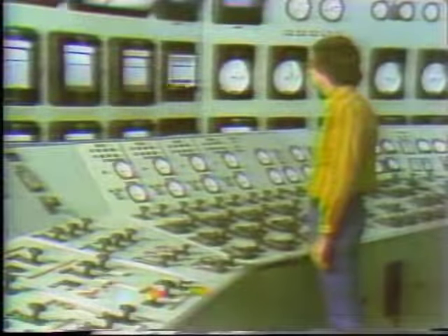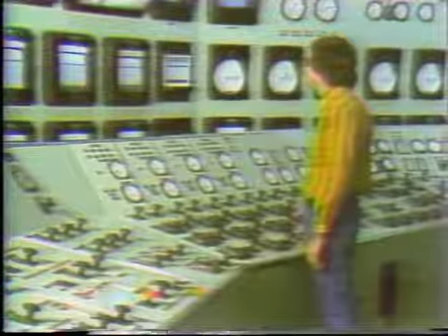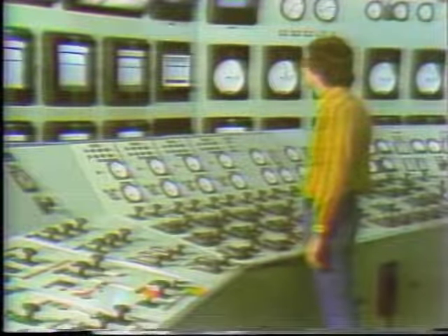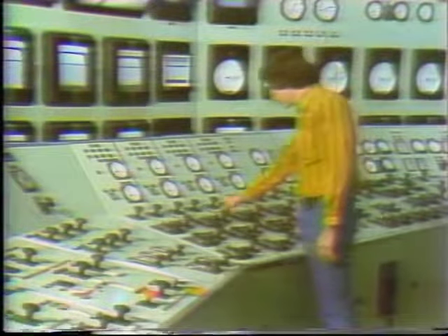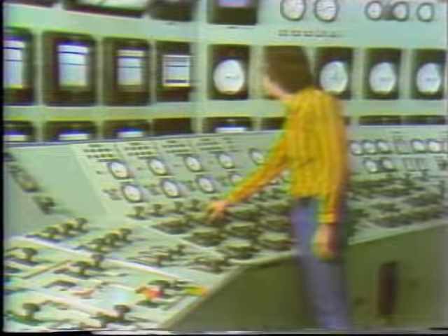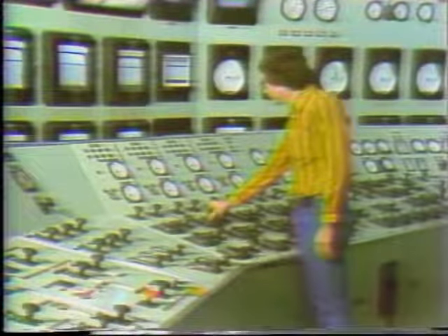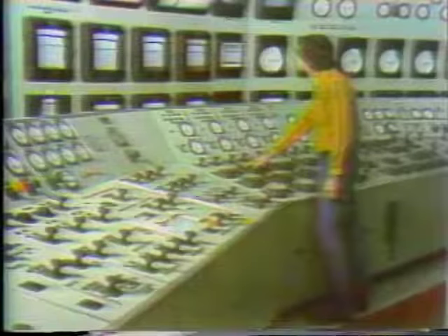Now, while all of this is going on, the operator is making routine checks of the flow rates and comparing them to what he has seen under the same conditions before. Should he spot what he considers a potential problem, for example, the combustion airflow rate may be too low, he may have to make adjustments to an automatic control system. In most cases, this will restore the unit to normal operating conditions. However, if it doesn't, the operator will have to take manual control of the faulty system.